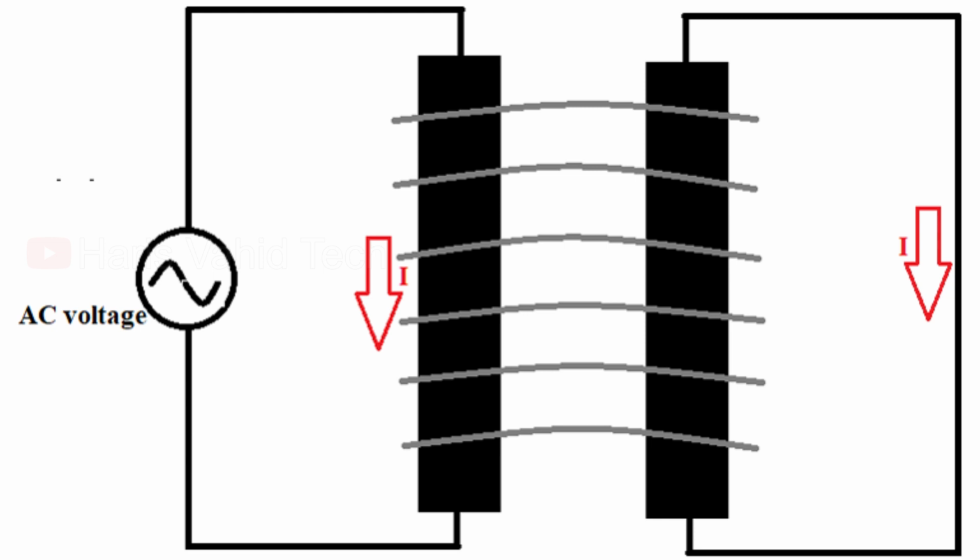Now let's remove the permanent magnet and replace it with another varying magnetic field source like this. Now an alternating voltage source and a conductor are used to generate a varying magnetic field. After the conductor loop is brought near to the magnetic field range, we can see an EMF generated across the conductor. Because of this induced EMF, we will have a current flow. The magnitude of induced voltage is proportional to the field strength experienced by the second loop. So, the higher the magnetic field strength, the higher the current flow in that closed loop.